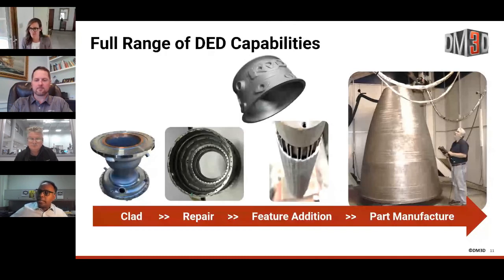Multi-material manufacturing is another great attribute to the AM technologies, and in particular for DED, it's a great attribute because you are pushing the powder into the melt pools. You have the ability to change the feedstock and switch from material A to material B or to material C, and apply multiple materials in the single build.